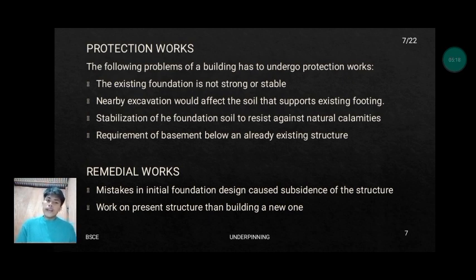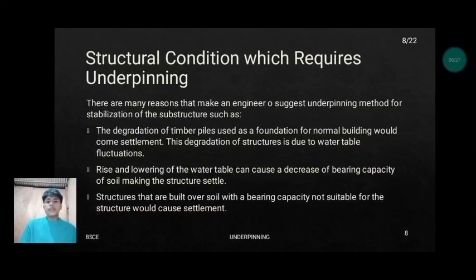Moving forward, we have remedial works. For remedial works, mistakes in the initial foundation design caused subsidence of the structures. Work is done on the present structure rather than building a new one. Moving forward, we have structural conditions which require underpinning. There are many reasons that an engineer suggests an underpinning method for stabilization of subsidence, such as the degradation of timber piles used as foundation, which causes settlement.